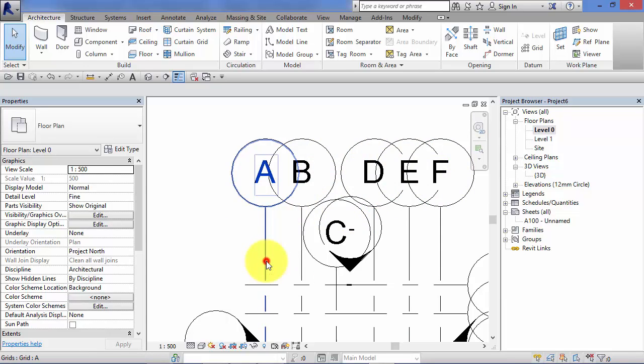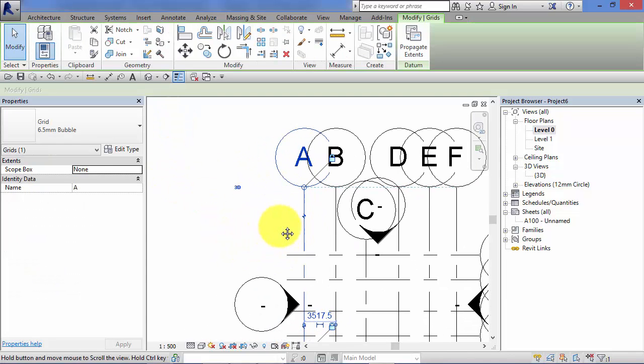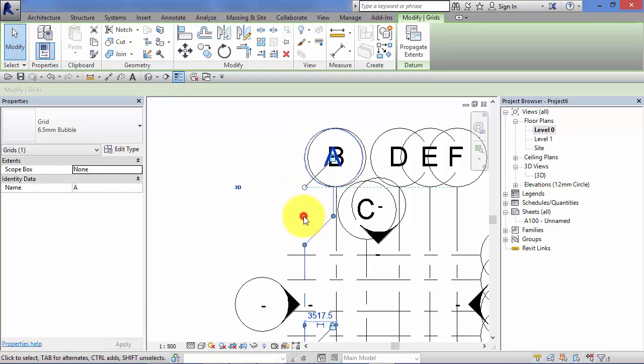So if we select that first grid line, we've got the option to add an elbow. Remember, it's that little sort of chevron icon there near the end of the line. If I click on it, it adds an elbow in, or a crank if you like. The line is now cranked, and there's a little grip there on the elbow. So I drag that over.